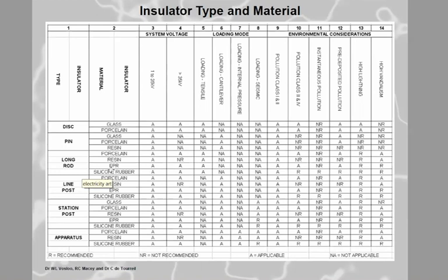Right, so now, if you take a look, with EPDM the surface cracks open. What happens to the pollution? Into the cracks. What happens to the area? Ta-da, goes big. What happens to R? Down. What happens to I? Up. See, rho L over A. And then the other material which you can get for the long rods is silicone rubber. What happens now to the area?